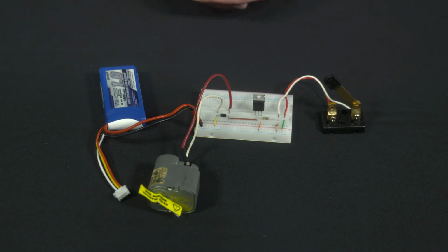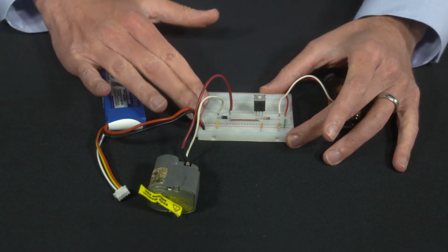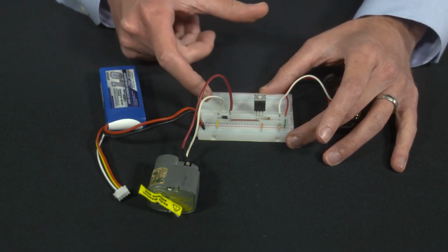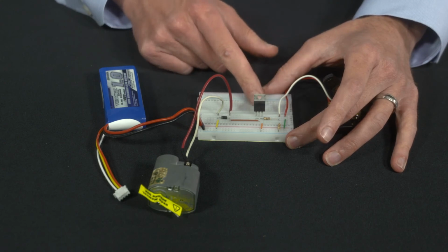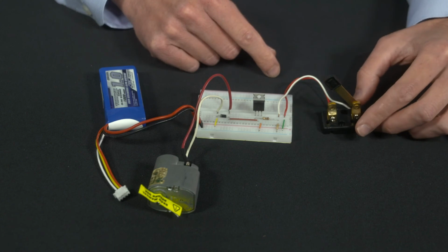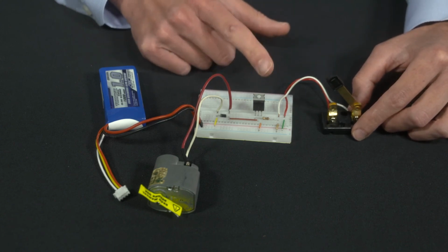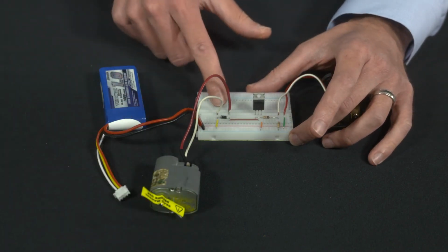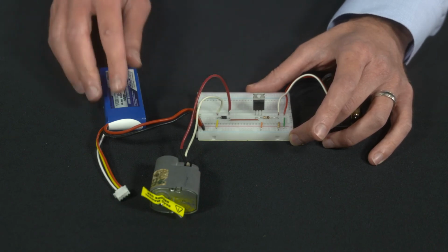Now that we've talked about building basic motor driver circuits using MOSFETs, let's see an example of one. So here we have the same basic motor driver circuit we've been talking about in this lecture, where we have a MOSFET, we have a flyback diode, and instead of driving the gate of the MOSFET with a microcontroller output pin, we'll just drive it with this switch, which will set the gate of the MOSFET high when we close the switch. So we also have our motor here, which is hooked in parallel with the flyback diode here in black, and we have our battery.